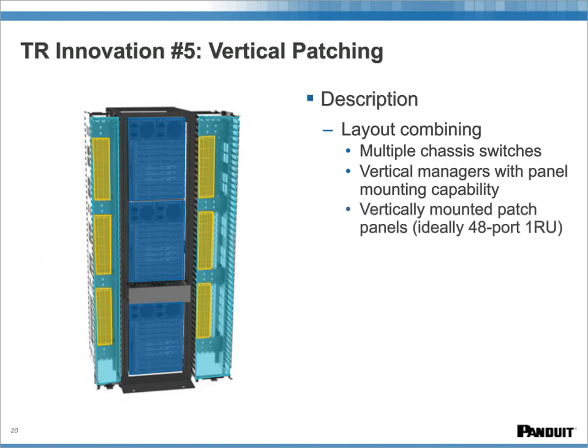In the yellow, you can see that we've got our vertically mounted patch panels. Here again, these ideally are 48-port 1RU panels because we want to take maximum advantage of this limited space within the vertical manager.